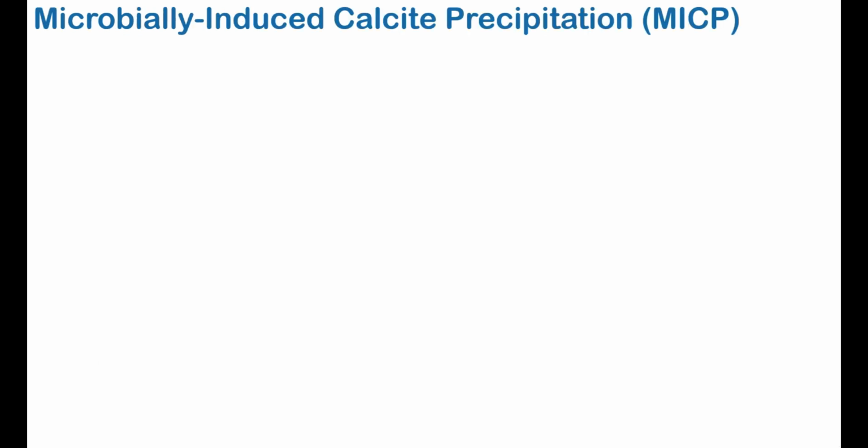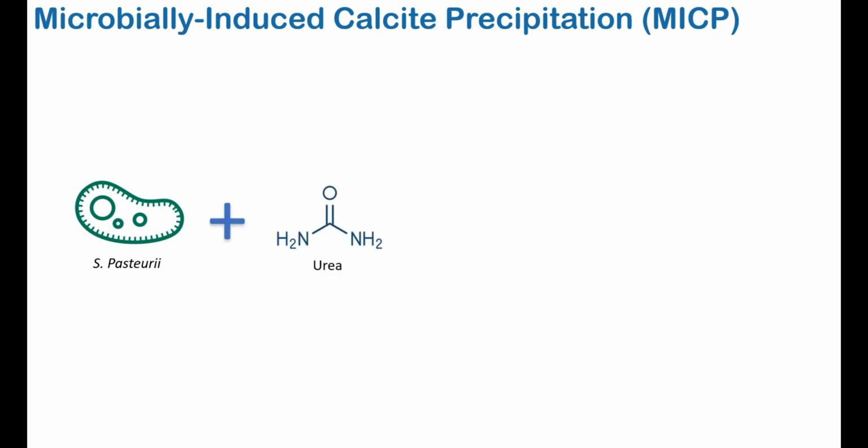In order to address the aforementioned concerns in an environmentally conscious manner, in this study, the co-disposal technique is further explored together with a naturally occurring phenomenon known as microbially-induced calcite precipitation. Bacteria such as Sporosarcina pasteurii have the unique ability to produce significant volumes of urease, an enzyme that catalyzes the hydrolysis of urea into ammonia and carbonate.